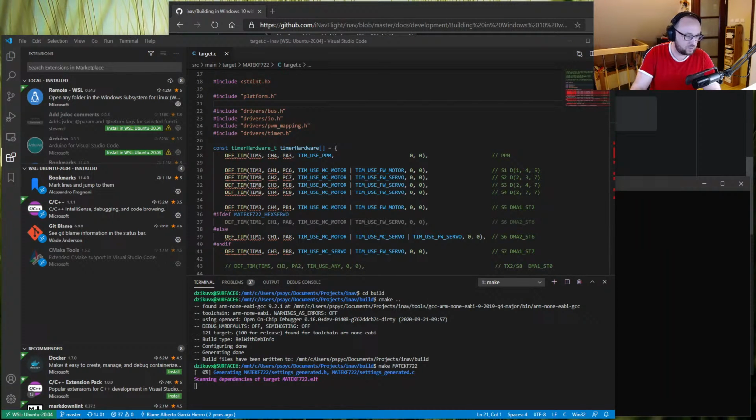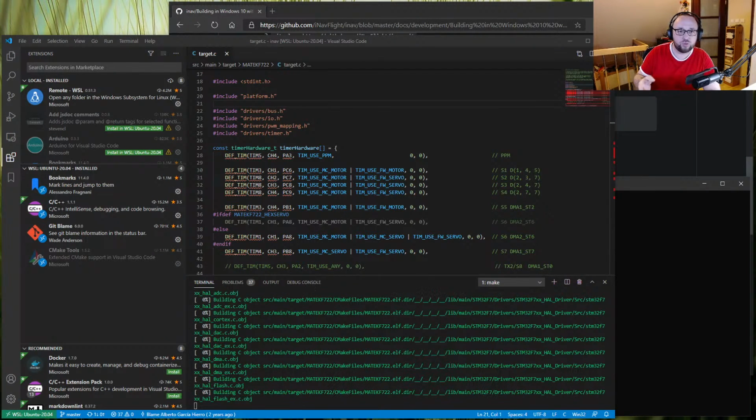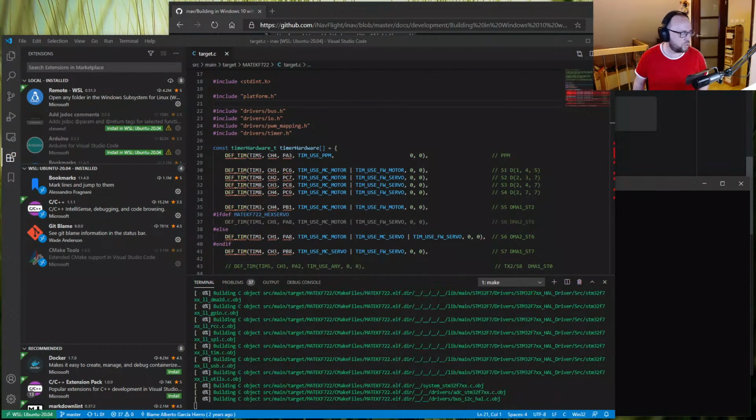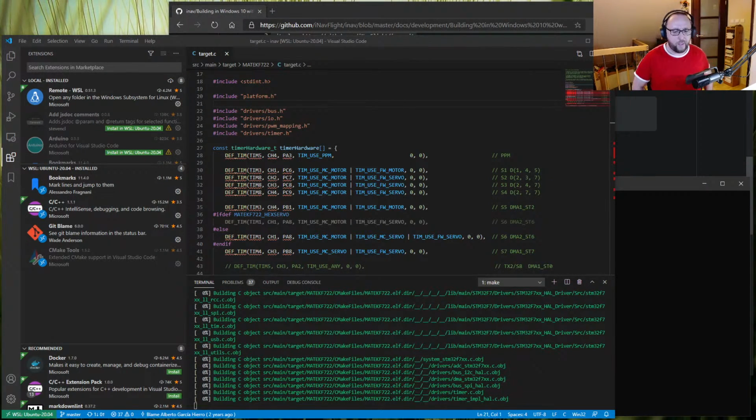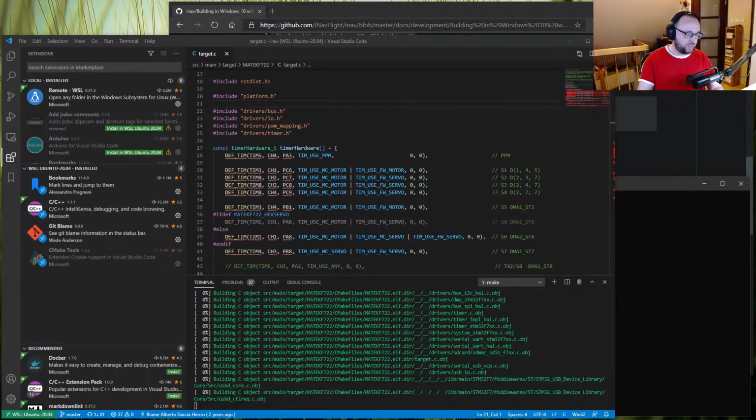Micra10 FPV asks if there is a way to change motor direction in INAV, not BLHeli Suite. No, rather not. I know it's technically possible for INAV to speak to BLHeli_S and BLHeli_M, because the protocol over there is open and you can just reuse it. However, BLHeli_32 has a closed source protocol, and this is not doable, so unfortunately you have to use BLHeli Suite to connect to those ESCs. I'm not sure if maybe Raceflight Falco X is doing something with that, not really 100% sure. But no, to change the motor direction, you have to use BLHeli or just swap any two wires from the ESC to the motor.